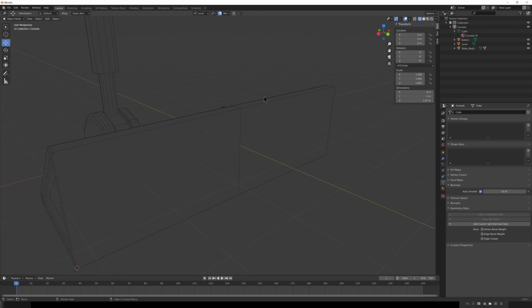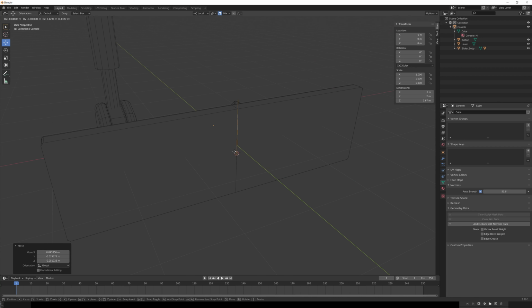Now the wireframe here, even if we select off the object, we're still going to get a silhouette of all the edges. And that shows us that we have this seam right here down the center, and we can use that to better pivot our cursor. If I hold down Shift and right click, you'll notice because I have center of edges selected under snap here, edge center, you'll see that it snaps right there. And that's actually a pretty good spot for this to be, either here or down here or up here, whatever ends up working for you. I'm going to choose this spot right here. I think that works well for us.